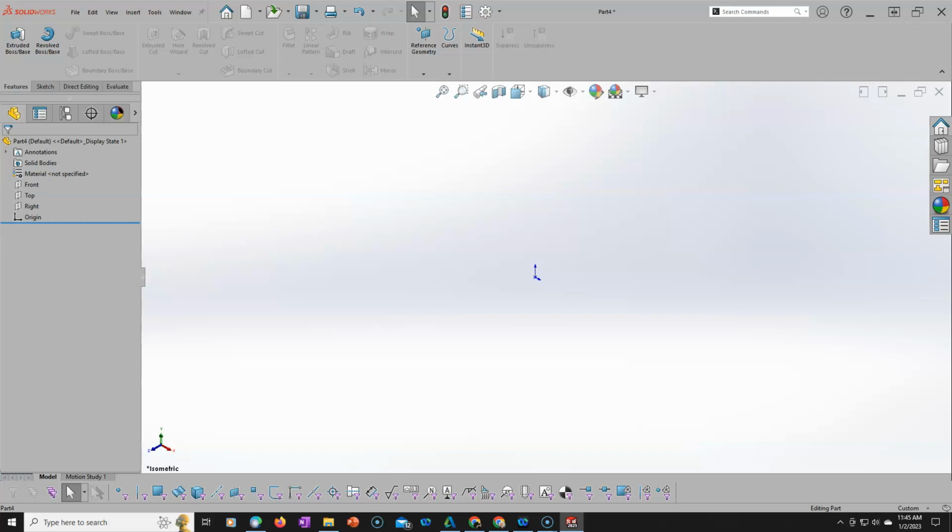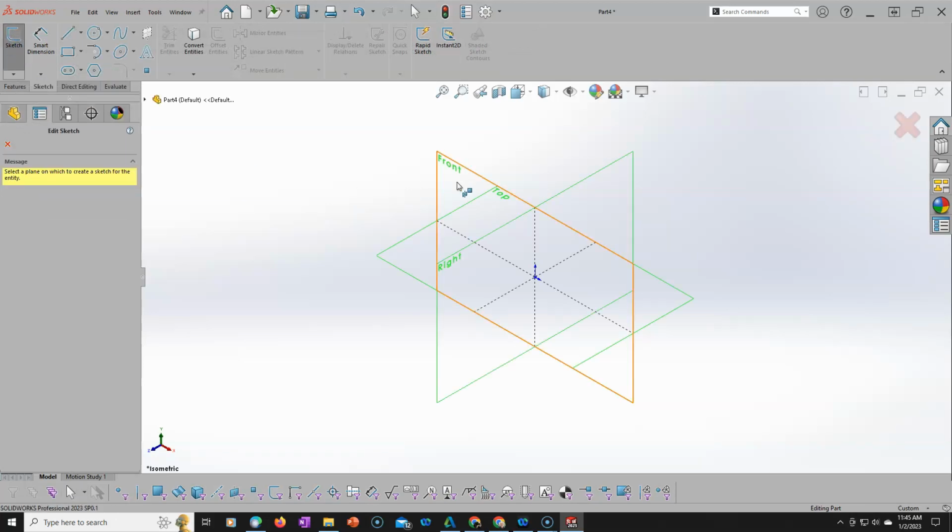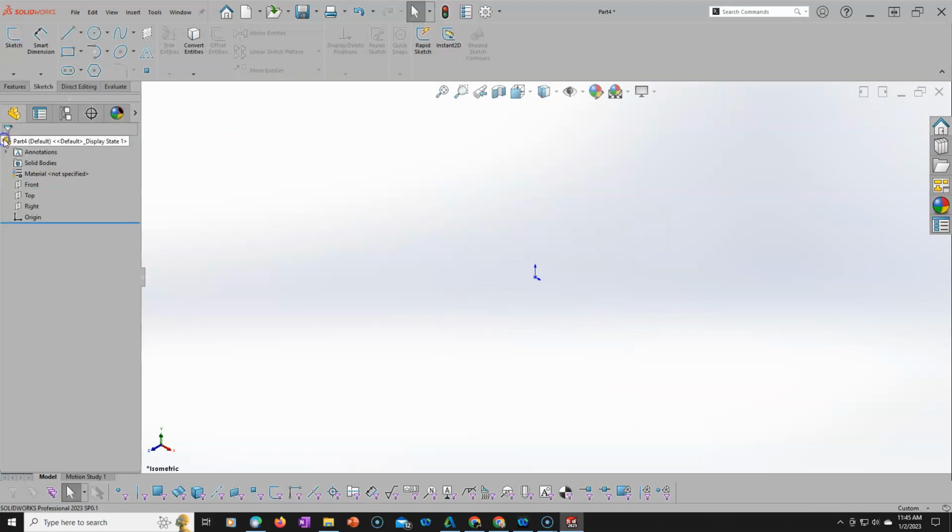All right, so to create our geometry, we are going to pick a sketch plane. So we did the sketch, and then pick the plane. That takes a little bit, but if I come over to the front and either left click and go to sketch, top, go to sketch, right, go to sketch, that puts me immediately into a sketch, and with that rotate normal to view.